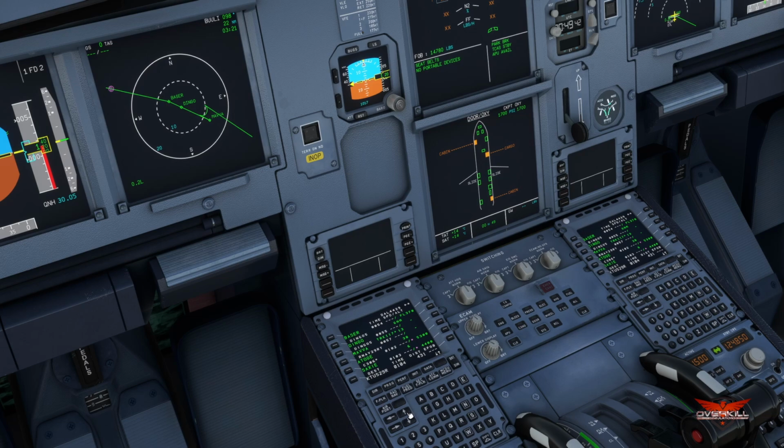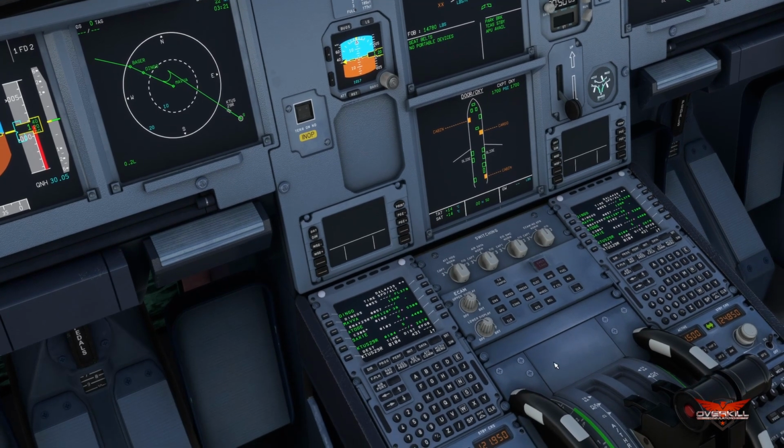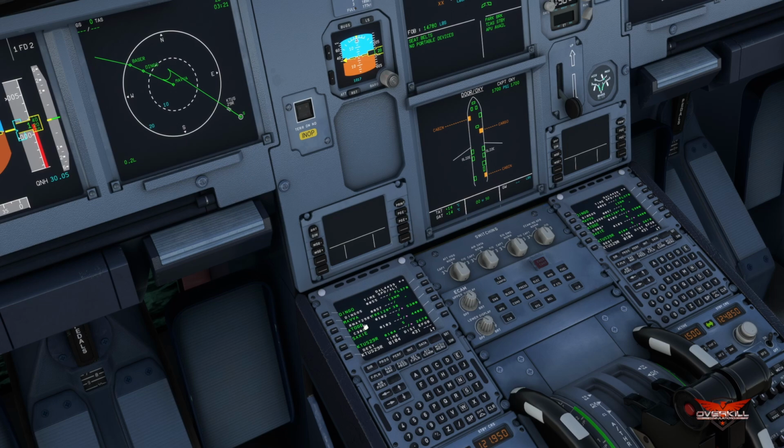point onto the approach, or via onto the approach, we're supposed to be coming for 29 right. 29 right is going to be an entry from this direction. We're going to be landing from the southeast. Okay, so in order to do that, you can see what we've got going on here is it's got us basically flying directly down onto the runway, and that just doesn't work. That's going to be a 11 left approach, which we don't have. So we need to make an entry after MCDU and get us onto the right direction.